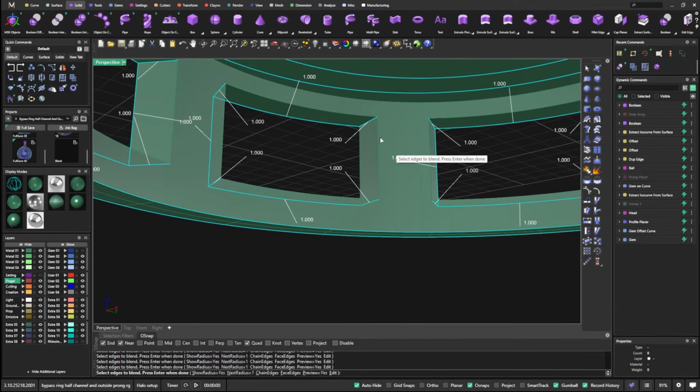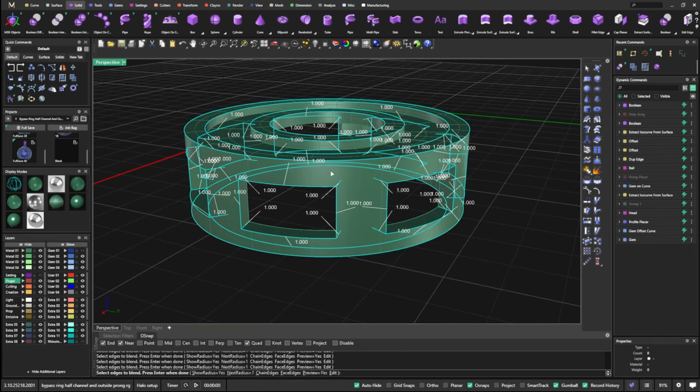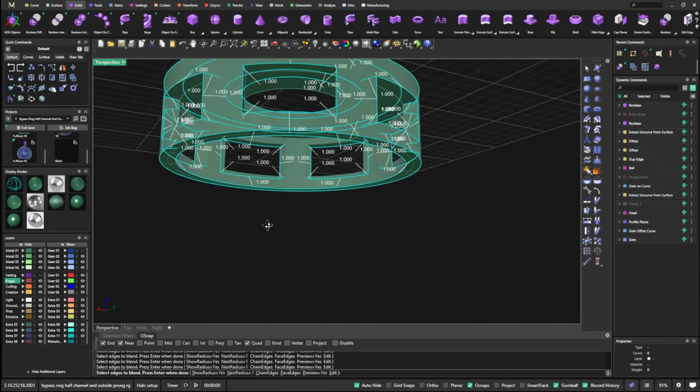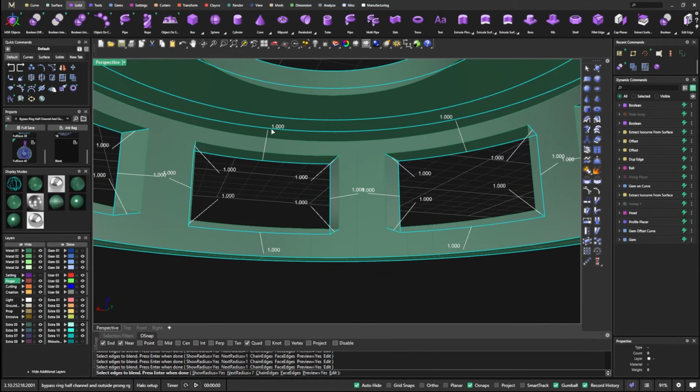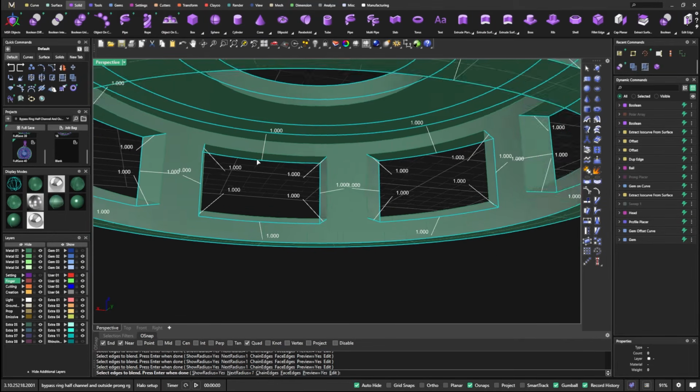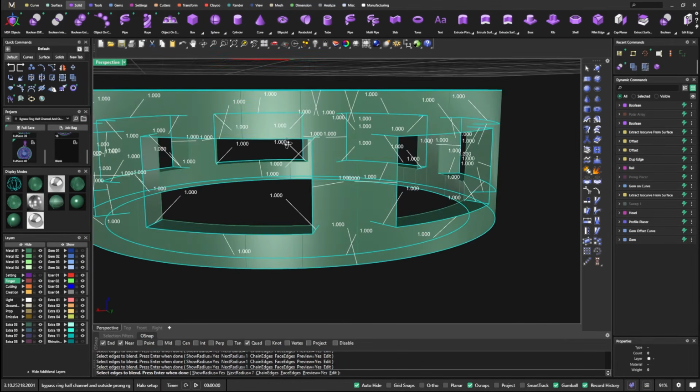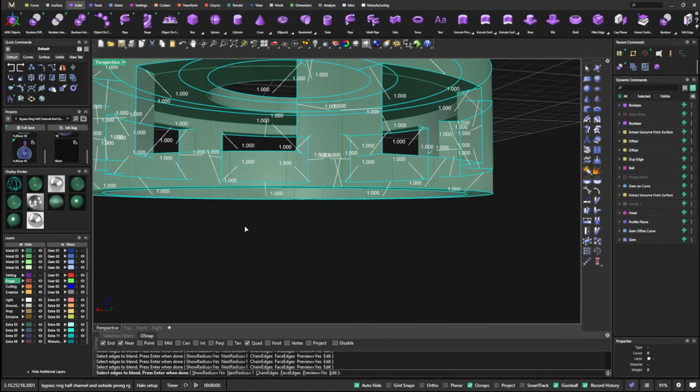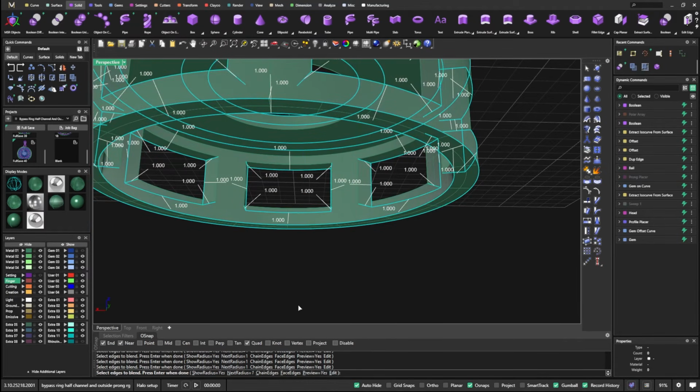I didn't get a grab. There we go. Okay, yeah. Now it's set at a 0.1, and I know a 0.1, or 1 millimeter, is going to probably blow, because I don't think there's a 1 millimeter space here between that. And I know these are a 0.8 supposedly, the bottom here, and a 0.8 across here. So I'm going to go ahead and right click to accept it.